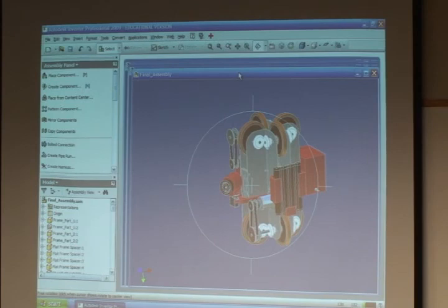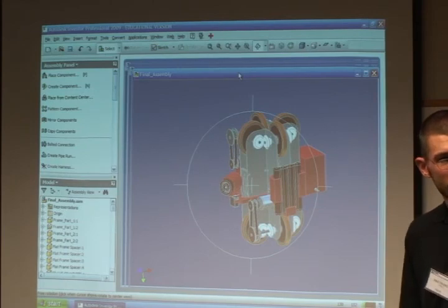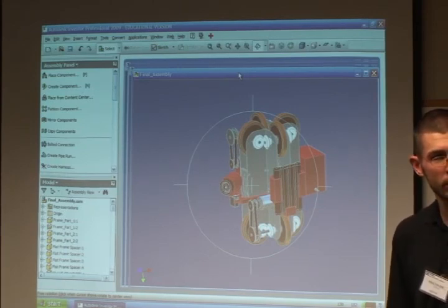You have to use those Allen heads. They have Allen heads that have Loctite built into them. Torx is definitely the way to go. You never want to put a button head or an oval head on the outer perimeter of your robot, because trust me, they'll take right off. Jeff took our tensioner screws right off the sidebar. They just went flying like popcorn.